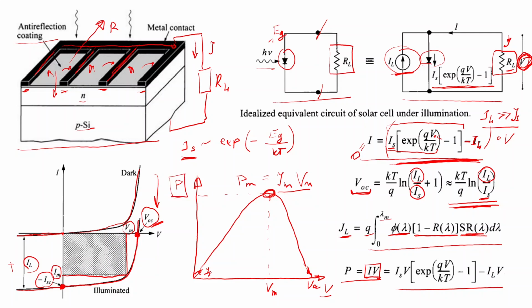So how we find this V maximum and I maximum, as I have shown you, we plot power, external power, which is product of current times voltage, versus voltage. Here we see this maximum point. We can already identify at which bias, at which voltage, we have this maximum power. Then we put this maximum power here on voltage axis. We extrapolate it towards the point where it intercepts with the current voltage characteristic of illuminated solar cell, and then we automatically find maximum current. Done.